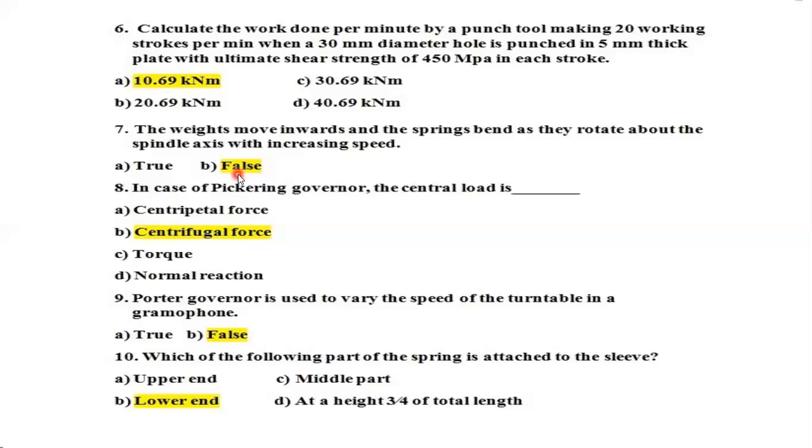So next thing, we need to calculate when the weights move inwards and the spring bends. Actually this comes under Pickering Governor. They haven't mentioned governor, but actually all these questions will be coming under Pickering Governor. So weight moves inwards and spring bends as they rotate. Actually it's false. For Pickering Governor, the weight will be moving outwards only.